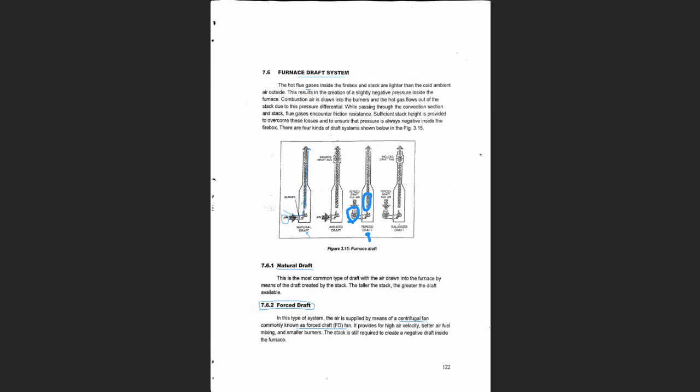لأنك أنت بتتحكم في كمية الهواء اللي تدخل إلى الفيرنس، وبالتالي تعرف كمية الوقود اللازمة، يعني ما تحرق أكثر من اللازم. جميل. طيب. So in the natural draft, no equipment, air flows naturally because of the density. In the forced draft, air is compressed by a fan or a compressor into the boiler or the furnace, and that makes the pressure inside the firebox above the atmospheric pressure.